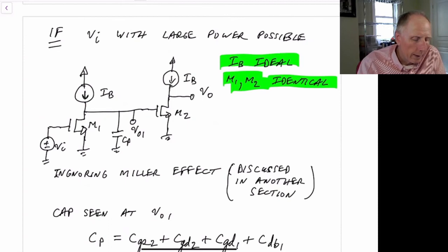So in the digital world, what we would typically do is a ring oscillator. So we'd build minimum size inverters, put them in a ring, and see how quickly they'll oscillate. And that would give us an idea of technology. So in the analog world, we'll just drive transistors all of the same size.